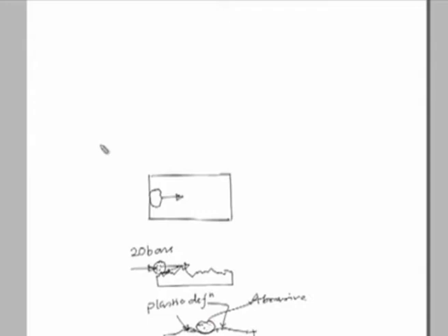So, this is called fluffing of the abrasive particles on the workpiece surface, which also causes this lip formation on this material, and on subsequent progression of these abrasive materials through this workpiece surface causes the work hardening on these lips, and then subsequently these lips are removed in the form of microchips.